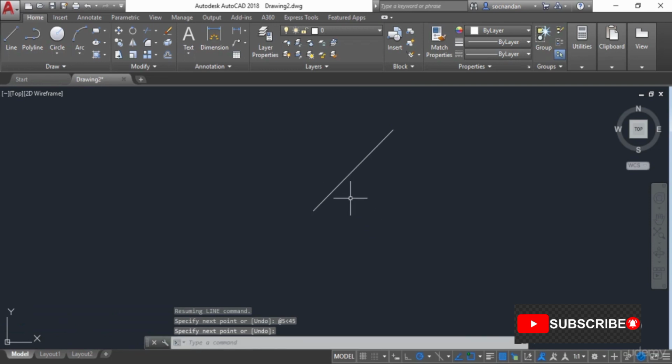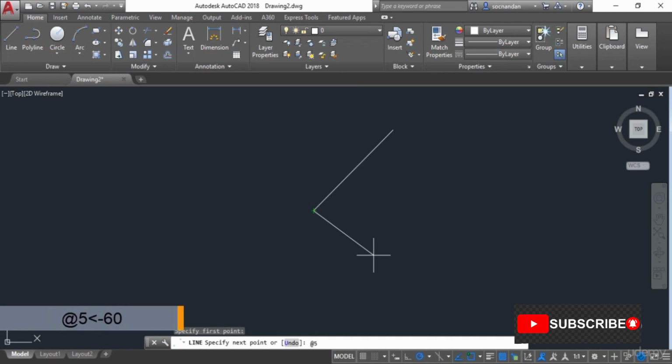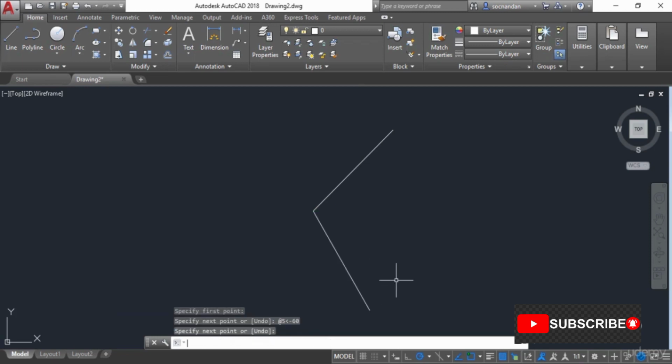Now let's make another line which starts from the same point, but this time it should be inclined to an angle of minus 60 degrees. So let's type @5, the length of the line, angle sign, minus 60. Since we are entering a negative value of angle, the line should be made in this lower direction. So let's press enter, and yes, we have this line in this lower direction.